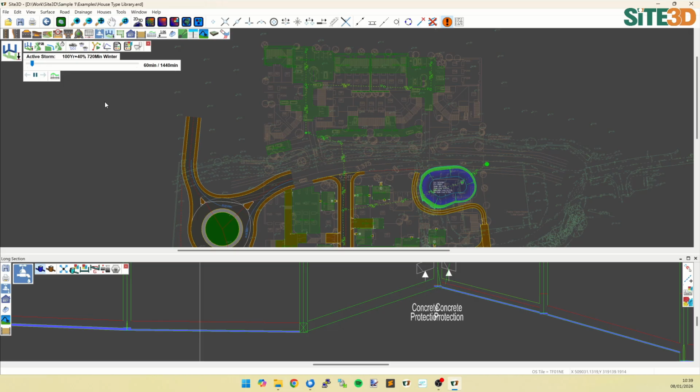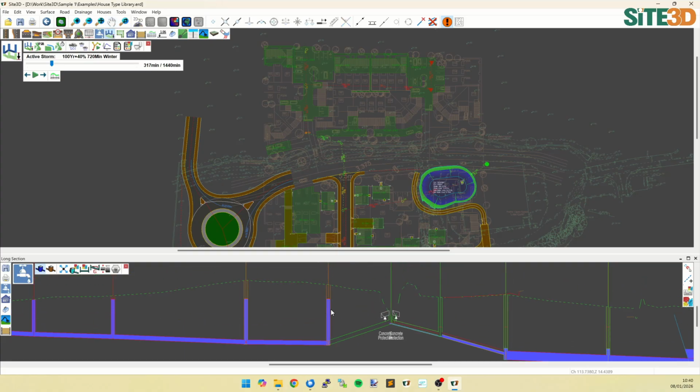In this case here we haven't reached 0. It's still going along, but it's quite a long storm, so I'm just going to skip forward. And you can see it'll keep going. We're getting our 2 liters per second flow rate coming out here. It backs up a little bit because obviously there's more water coming in than there is going out. But once we get past that maximum stage, it will then start to lower the water because it is pumping it out until we get to basically 0.